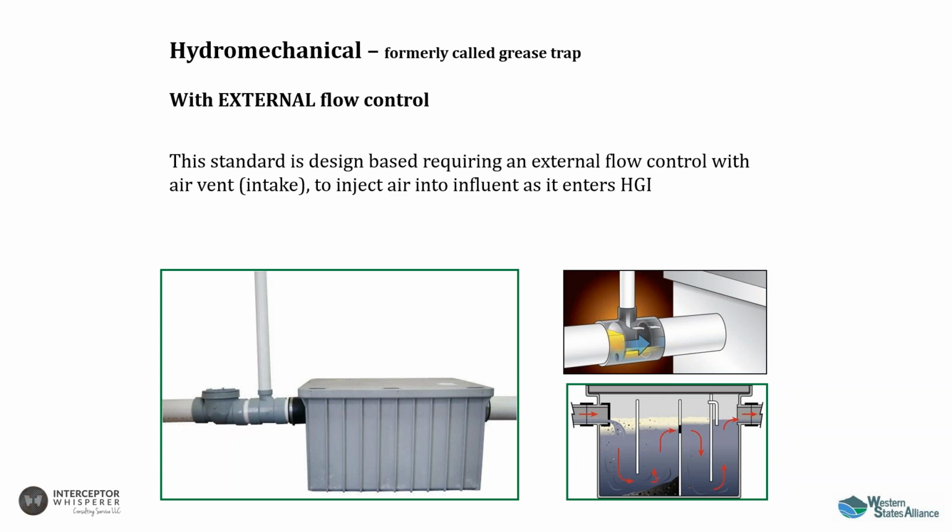And there are some workarounds people are trying to use to get away with some challenges between the standards and the codes. So when you're looking at a hydromechanical interceptor with a PDI label, as an inspector, I want to make sure that the device is compliant, which means I want to make sure that it is performing correctly. And the only way that it can perform correctly is if it has its flow control installed. So as a pre-treatment inspector, you certainly want to verify that.